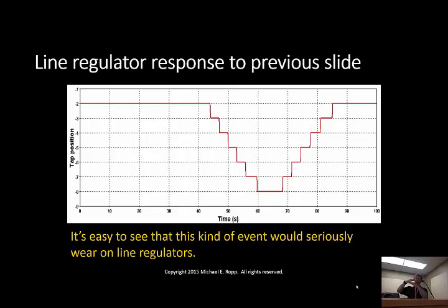Because the inverters are already full throttle, they're maxed out. They're not max power tracking. So sometimes some of those divots actually will be completely in that space of capacity that's above where the inverter is operating now. So yes, a lot of the smaller transients will in fact go away, and the bigger transients won't be as big. That's one benefit to doing that.